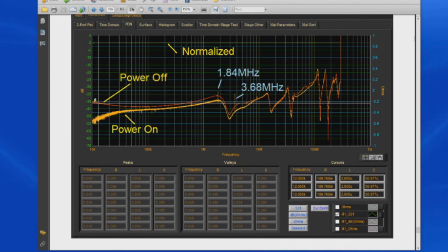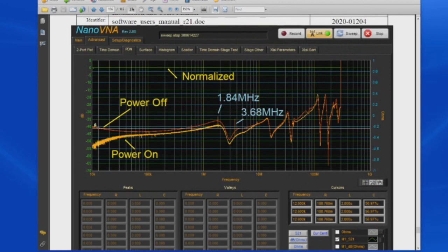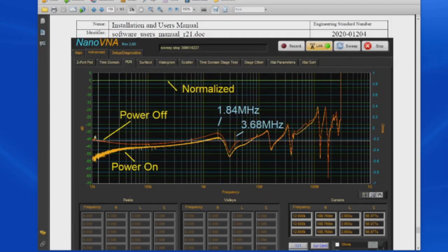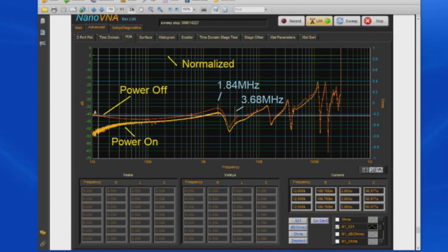Here's the harmonic of it. And we notice all these ripples. Each one of these is the bypass capacitors that we've got stuck across the chain. This is a lot more typical of what you'll find when you're looking at a PDN. And again, what we'd like to do is smooth out some of these peaks, not just the high ones, but the low ones as well. All of these can cause the emissions problems.